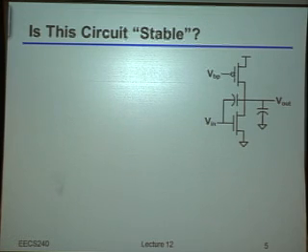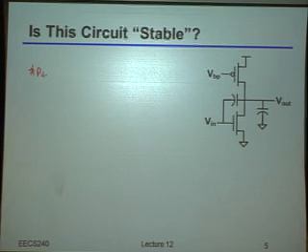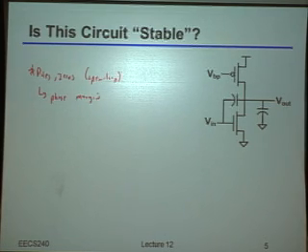Okay, there we go. So first you said you're going to figure out the poles and zeros. Now, by the way, when you said the poles and zeros, do you mean open loop or closed loop? Open loop, okay. So we can check the open loop poles and zeros. And then you said something else after that. Check the phase margin. Okay, there we go. You could check the phase margin once you've done that. That's indeed the very common thing to do. Anything else?